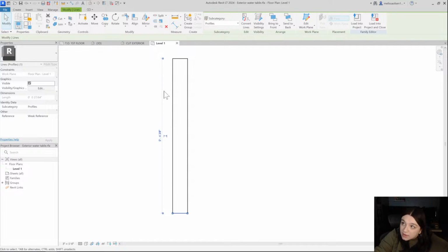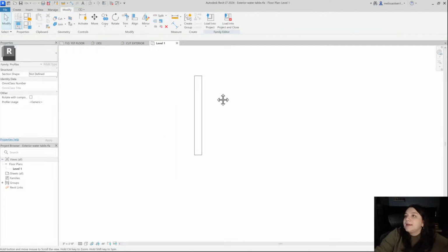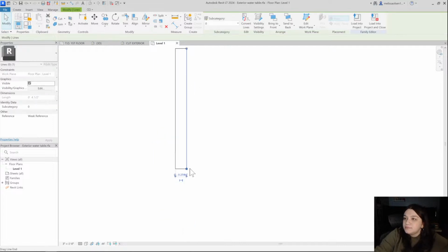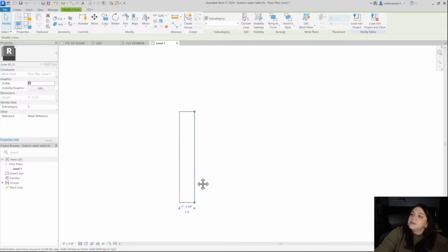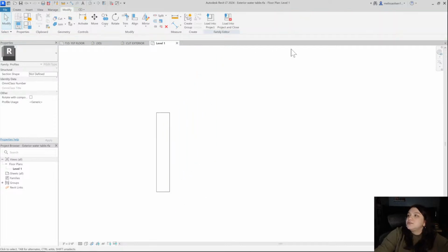So I can see here that it does come on. So the piece height right now is 4 3/8 of an inch. So I would just change it to 4 1/2 to be like a standard piece of trim. And I could use that in both the water table and the side of the wall. So I'm just going in, I'm going to change this to 3/4 of an inch, because that's usually how thick wood is.